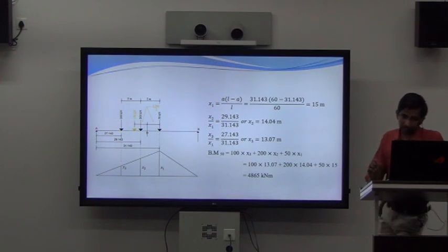So please understand, this maximum means when this train of loads moves from one support to the other, the bending moment under 50 kilonewton will have different values, and at a particular location this value, that is the bending moment coming under 50, will be maximum, and we have found that value. For that, we have kept the resultant and the required load as per our condition. So this is how you do a problem like this.